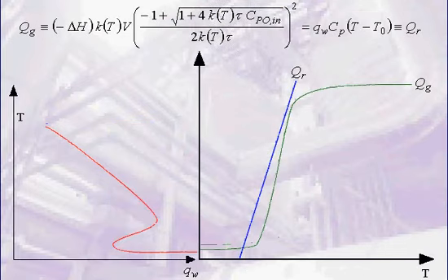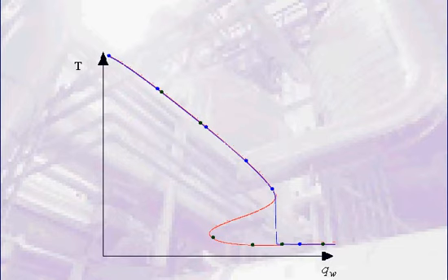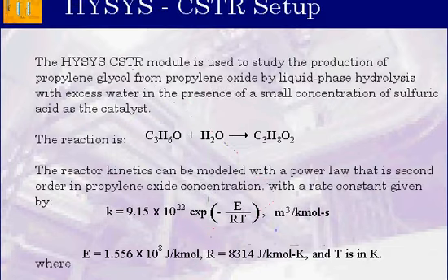from the sensitivity analysis. With increasing water flow rate, the high temperature steady state solution is obtained, jumping to the low temperature solution after passing through the multiplicity region. With decreasing values of water flow rate, the low temperature steady state solution is obtained, jumping to the high temperature solution after passing through the multiplicity region. The multiplicity region is typical for CSTRs operating both adiabatic